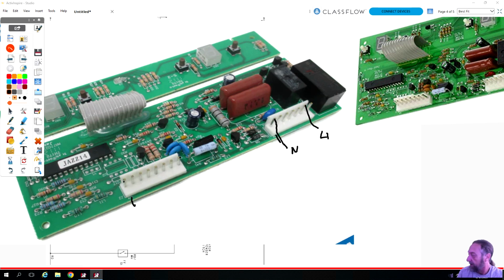Now it is sort of important if you do something like this with these connectors. When you get old boards like this, I want to show you guys something. When you get an old board like this with these connectors, cut them off the refrigerators. If it's going to be thrown away, cut these off the refrigerators. If you look here, you see these metal pieces. I don't know if my screwdriver is big enough. You press down, you press the wire up, and you press down on that little piece of metal like that, squeeze it in, and you can pull these wires off.